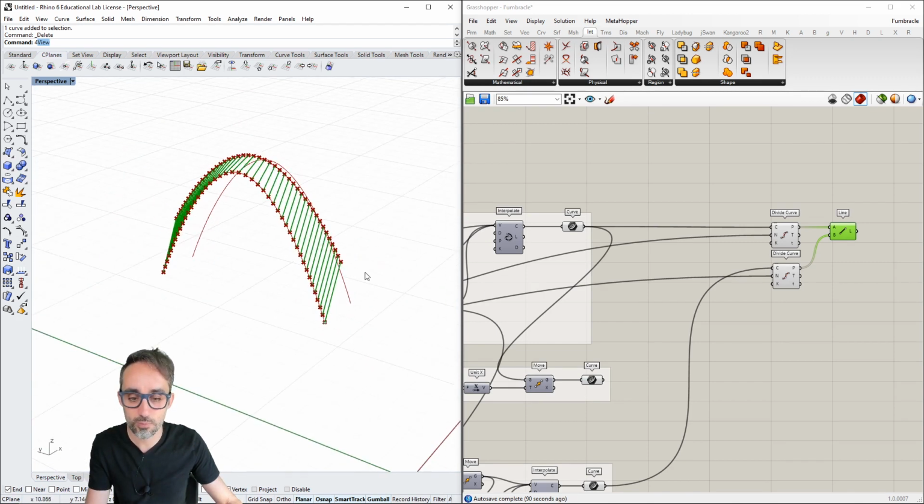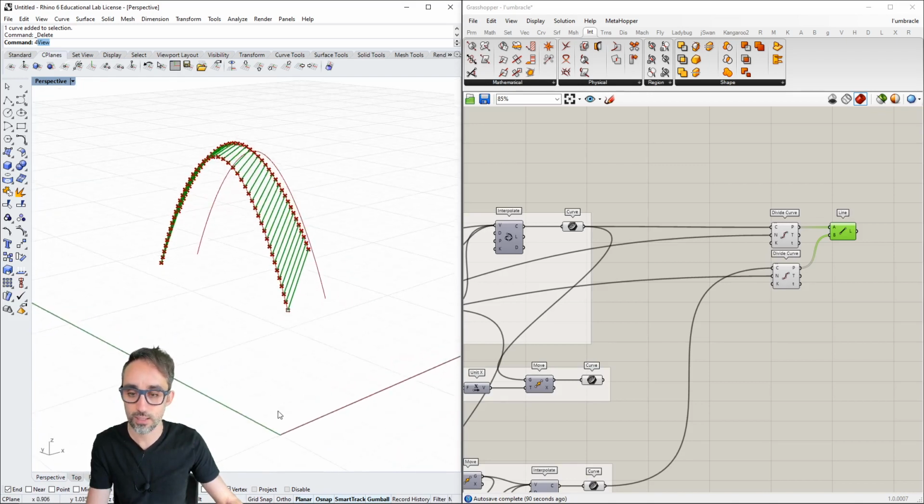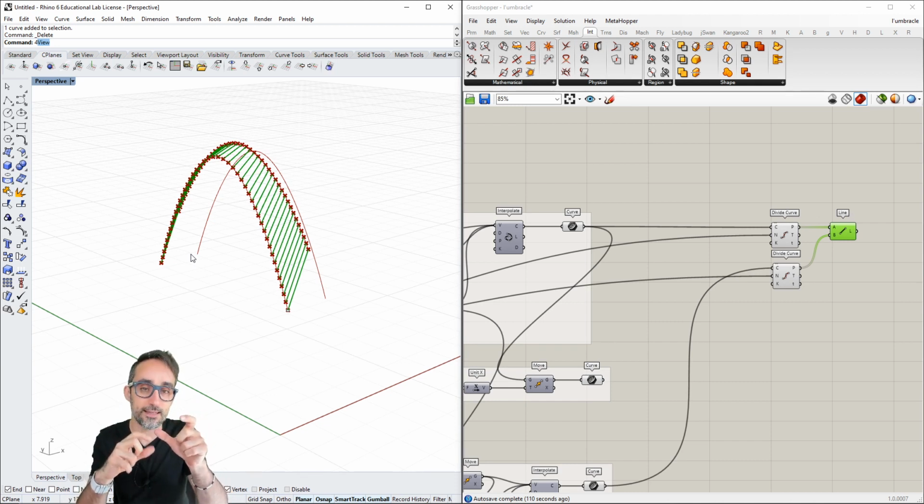I think a good method could be to create a horizontal plane here, then cut the original curve along this plane to find the 2 points where the offset is already set and where we would start the ribs. Then if we find the parameter at which that plane cuts the curve, we can split the curve at those parameters and use the subset of that curve.